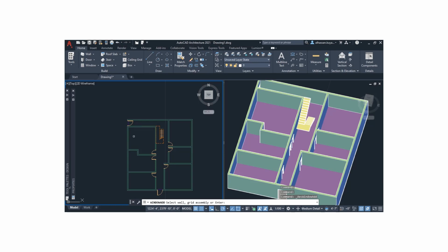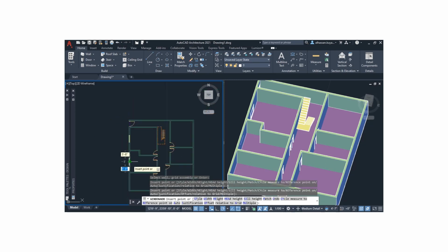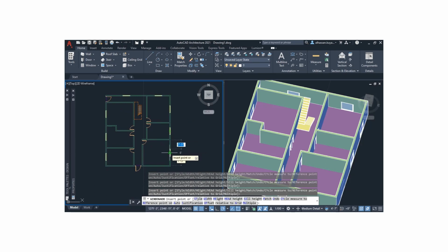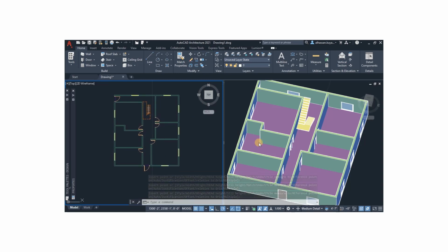So we're going to position the windows to any position we want. To position it, we click on the wall and you see the position will appear. So now we want to click on this auto so that we'll be able to position the window automatically. We want to position all windows at the midpoint of the walls of the rooms. So when you click on auto, then you'll be able to select this as the midpoint of the interior wall. Click here also, midpoint of the interior wall. Here again, here also. So position every window. So that's it. We've done the windows.